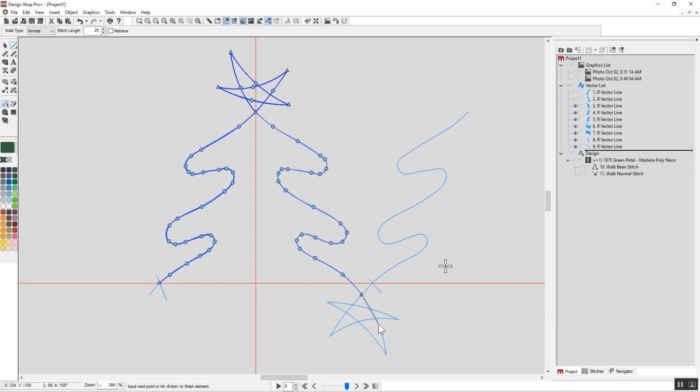Left click, now I'm going to do my star again. Right click, left click, right click, left, right in the middle of the curve, left at the end point, right in the approximate middle of the curve, left, right, and where my repeating pattern stops, right there, I do a left click and I hit enter. So there's my repeating pattern now.